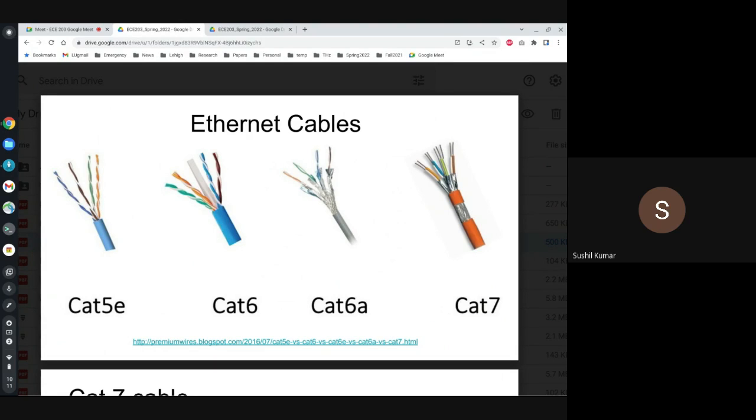In general, when you connect an Ethernet cable, it can probably do 100 megabits per second, which means the frequency that you transmit is of the order of 100 megahertz, but you can also go to 1 gigahertz. But do you see, there are 4 transmission lines bundled into this Cat7 cable. And obviously, the dimension of that cable is not of the order of wavelength.